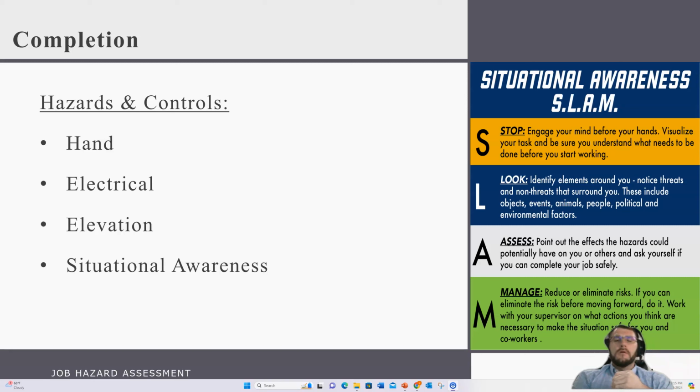Additionally, elevated work hazards, we got to prevent those by utilizing our harness, Fall Pro, with 100% protection with double retracted lanyards, lifelines, prevent accident injuries there. And additionally, we got the situational awareness practices. We want to make sure we don't have any slips, trips, and falls. Use proper housekeeping protocol. We want to make sure we don't have any pedestrian injuries. Use proper earplugs at all times.